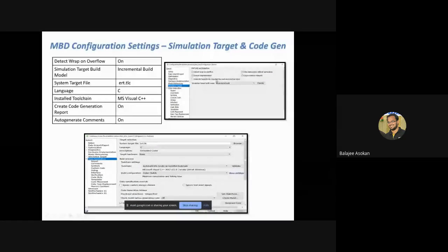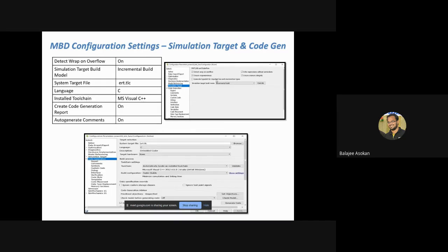Say, for example, an engineer is new to the job. He's trying to do some of the changes. He does some of the changes while he has missed some others. So where can he find it out? We were talking about this model advisor report, right? After finishing this, he has to run the model advisor report. Model advisor report along with my C code is a final deliverable file.